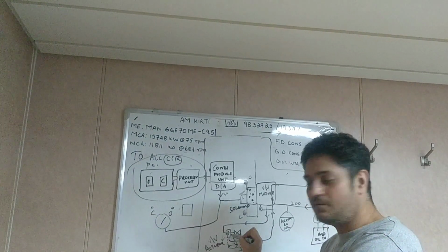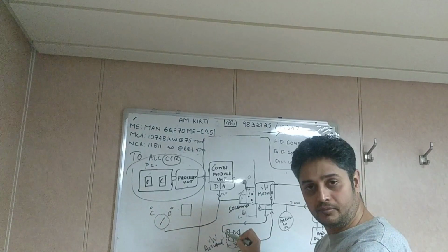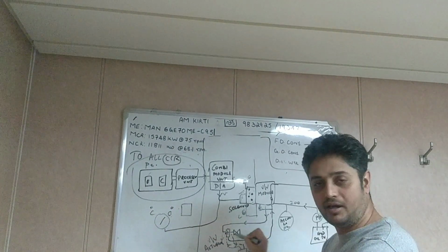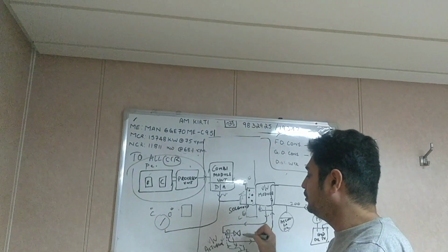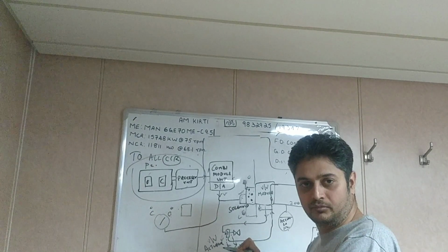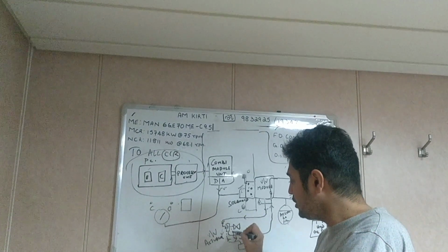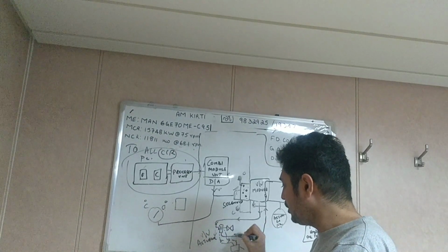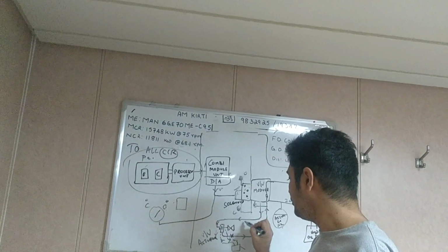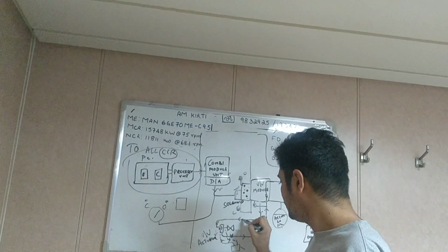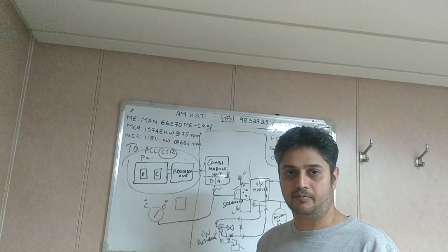You will have an arrangement here for emergency connection. You will have an adapter at the actuator. Ultimately the valve can be turned by the actuator, or if it is a small valve, you try to put the spanner here, after disconnecting. Every valve will have an isolation valve for inlet and outlet to do maintenance, and a bypass may also be there. You have to see the system.